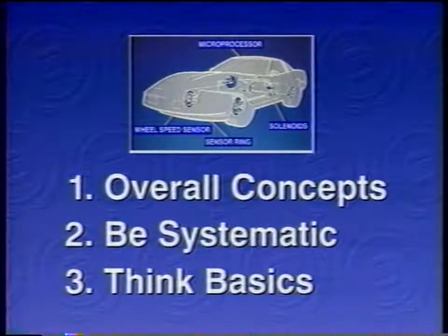Think basics. High-tech systems such as ABS tend to make most people look for exotic problems. A frayed wire or a broken sensor is much more likely than a damaged electronic control module.